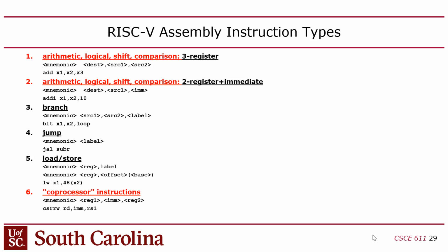That's what hardware does. In the assembler, if you use a symbol in there, the assembler has a symbol table where it takes the symbol's address and converts it into instructions that build that base address for you, that set the base register with immediate instructions, right? So when you write your code for Lab 1, you can use symbolic loads and stores, but you have to be aware that those are going to be translated to machine instructions. So the machine instructions are what you're actually going to be implementing in your hardware, right?